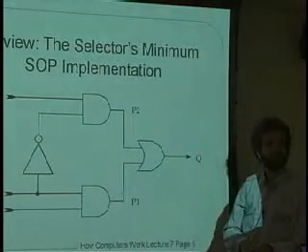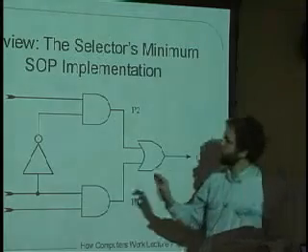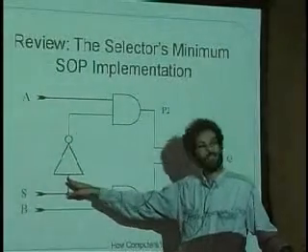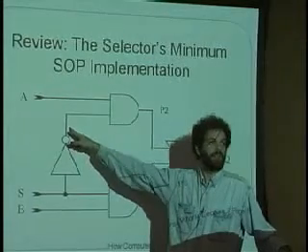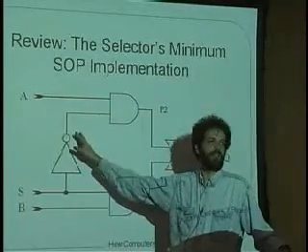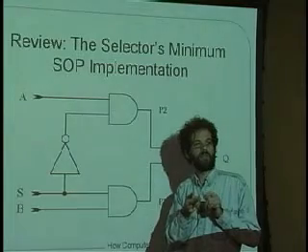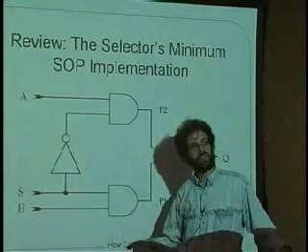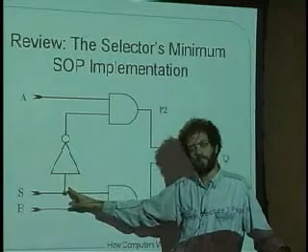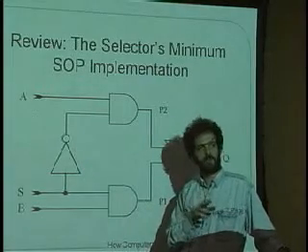Yeah, I can see now how the AND gate works, but how does the inverter work? Because it either takes away charge or it adds charge, right? Well, not exactly. This is the input side of the inverter, and this is the output side of the inverter here. So when there's a logic 0 here, a short time afterwards, a logic 1 is created over here. And when there's a logic 1 over here, a short time later, a logic 0 is created over here. So it's like an amplifier in that it takes an input signal and replicates it on the output, but it does an inversion of the signal. Okay, so it's not that there's one place where charge is being generated or taken away, and there's no memory per se on the inside of this thing either. It's just a logic function that's sort of taking the input, reversing it between 0 and 1, and then propagating it to the output. Does that sort of make more sense?